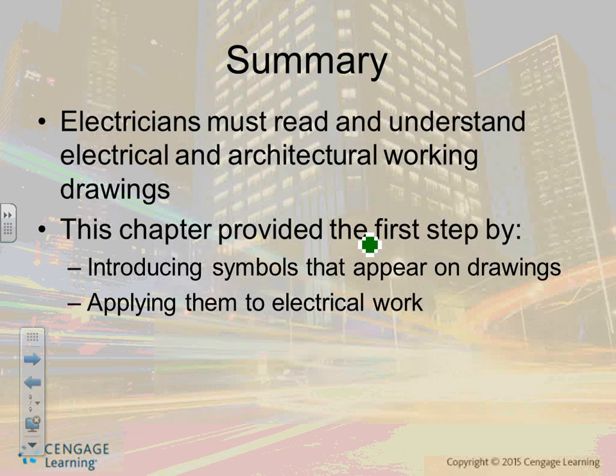Page 38, please. Page 38, raceway indication symbols. Look at the first one. Preferred symbol. Can you guys see that symbol? Conduit stop, terminal with bushing or cap if underground. Look at the one right underneath it with the circle. Conduit turning up. Look at the one with the dot. Can you see that one? This is conduit turning down.